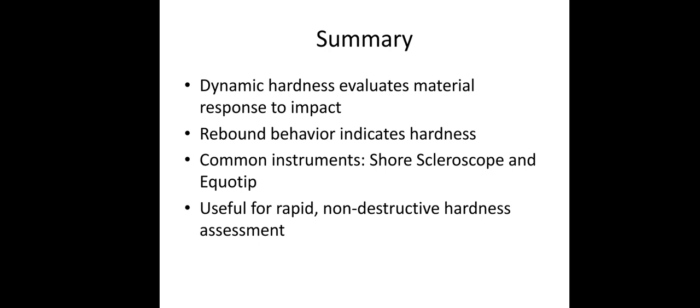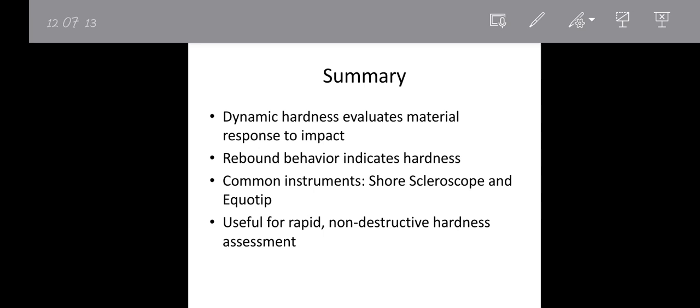Finally, we conclude this topic. Dynamic hardness evaluates the material response to an impact, and rebound behavior indicates the hardness. The Shore scleroscope and Equotip are common instruments in the dynamic elastic hardness test. It is useful for rapid and non-destructive hardness assessment.